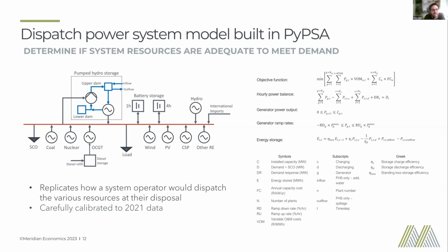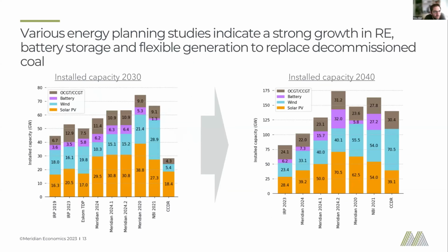And from this, we really got a lot of interesting insights, which were almost counterintuitive to a lot of stakeholders at the time, and just showing how adding variable renewables into a system that is so energy constrained makes a significant difference in terms of the operation of the overall fleet and the different assets, and that having more energy from any source allows you to keep more water in your pump storage dams and keep more diesel in your diesel tanks, and then you can dispatch that in other hours. So this has a significant effect in improving system stability and adding more load shedding resilience.